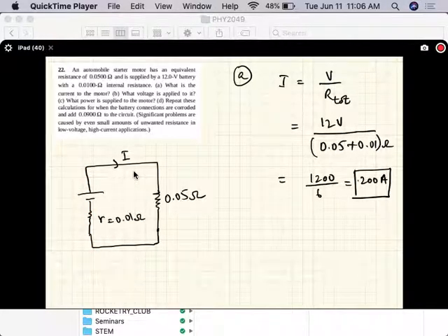And that's what an external load sees. So we'll call this VA, VB. So that's outside of the battery. For instance, this is 12 volts, that's the EMF of the battery and that's the maximum voltage it can provide. The motor is not seeing 12 volts. The motor is seeing this voltage.